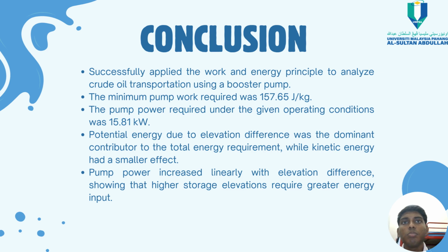From our calculation, the minimum pump work required was found to be 157.65 joules per kg, while the pump power required under the given operating condition was approximately 15.81 kilowatt. Our results show that the elevation difference has the greatest influence on the energy requirement. Compared to the changes in kinetic energy, the increase in potential energy contributes much more to the total pump work. We also observe that as the elevation difference increases, the pump power increases linearly. This means that transporting crude oil to a higher storage tank requires significantly more energy.